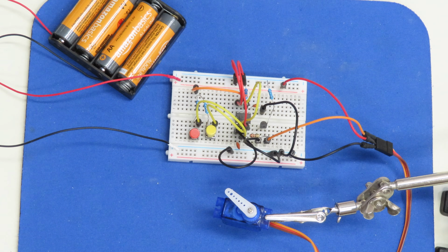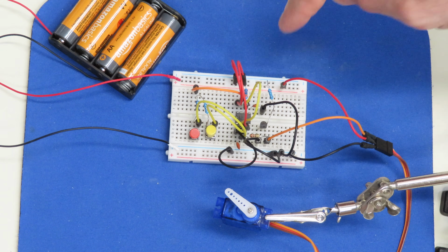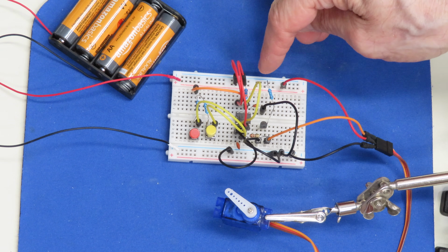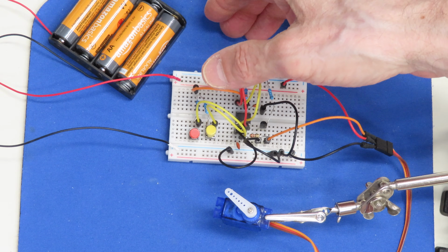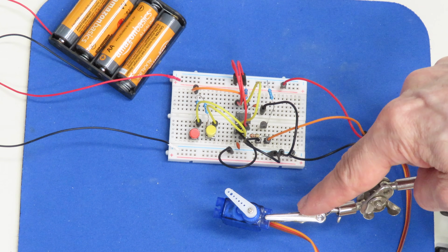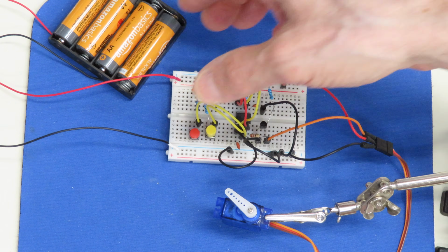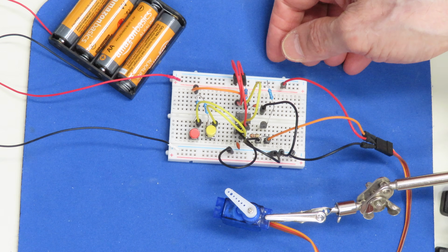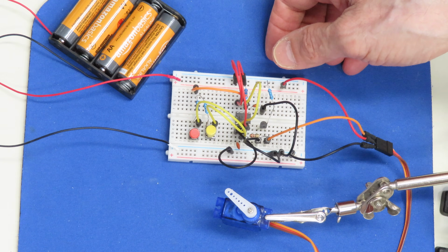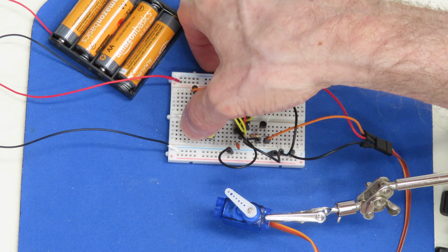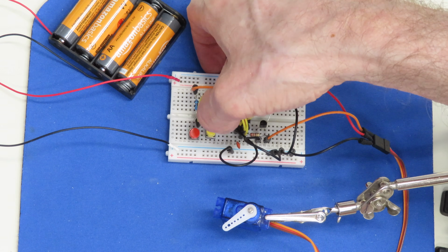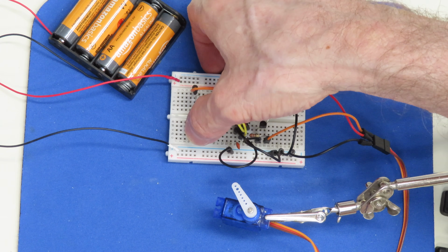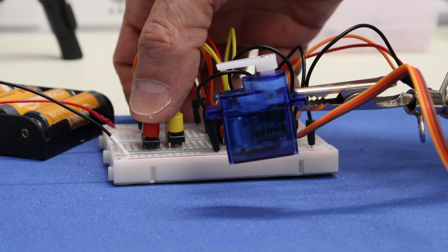And so here's my servo motor tester circuit, and as always, I've got it on a solderless breadboard. I've got my 2 push buttons, which should control the direction the servo is going, and naturally I have a servo motor connected as well, and this is being powered by a 6-volt power source, which is 4 AA batteries in this particular case. And so pressing this button should move it in one direction, and pressing this one moves it in the other direction. And it seems to work very well.